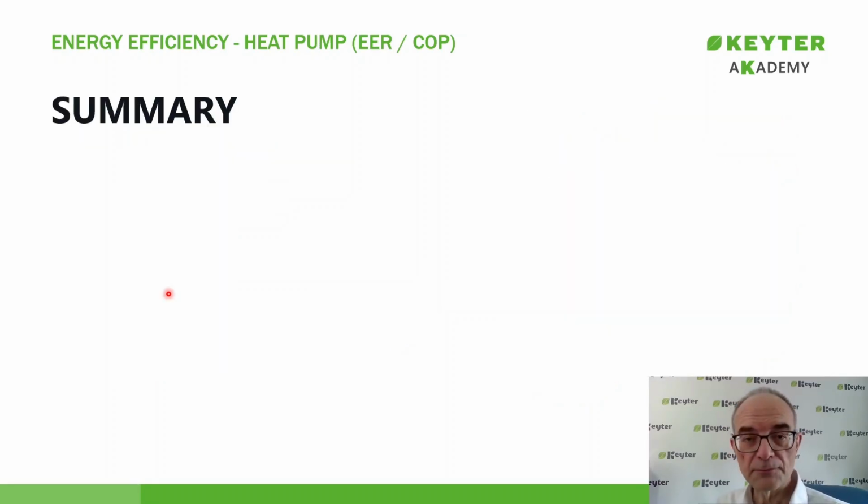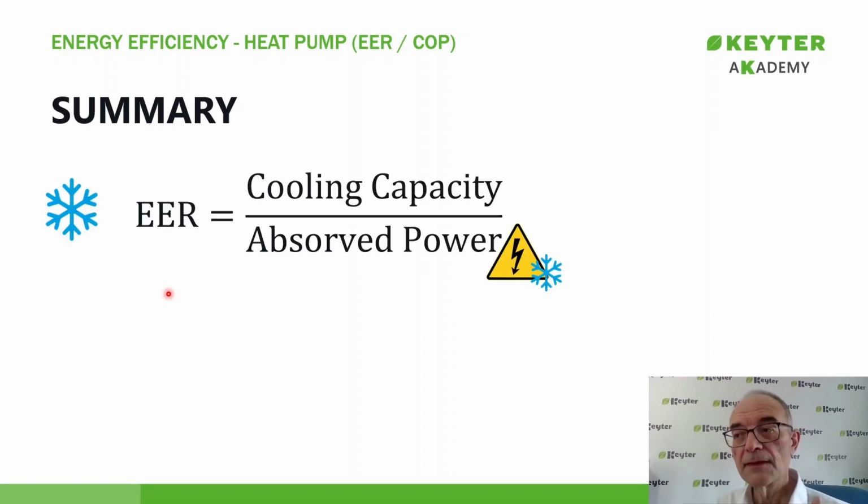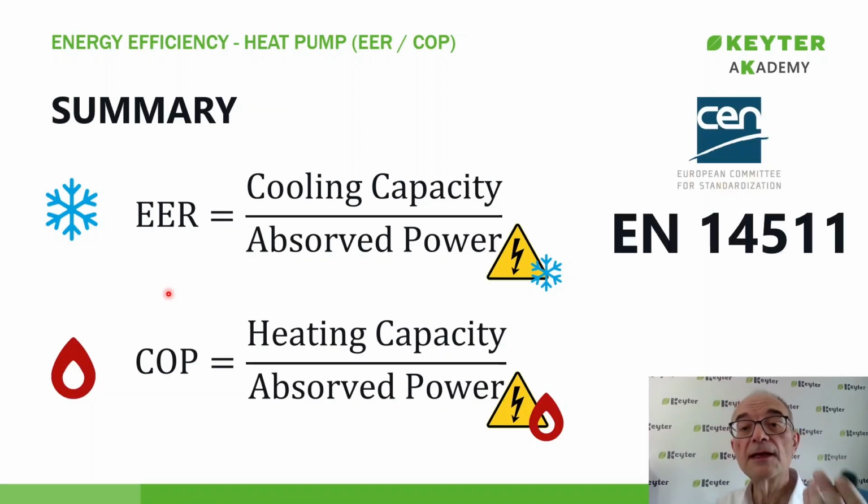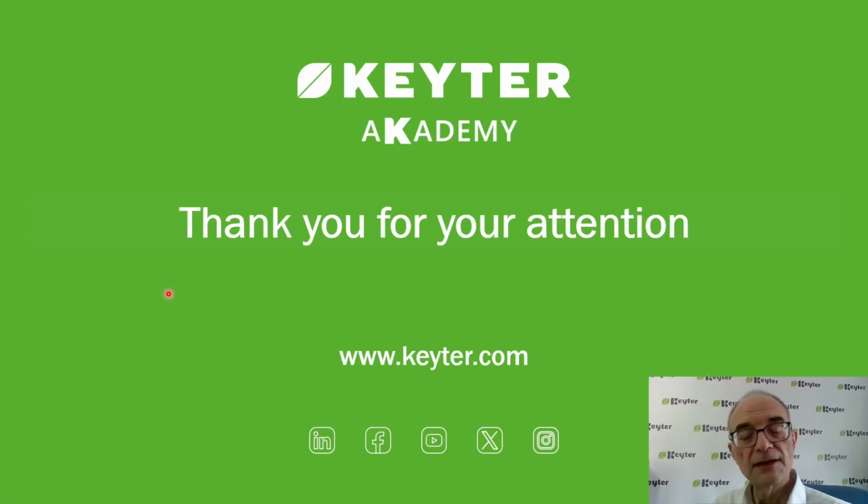To sum up, and this is the important part I want you to remember, for cooling mode, we'll calculate the EER, and it will be the ratio between the cooling power delivered by the heat pump and its energy consumption while operating in that mode. The COP is precisely the same, but now working in heating mode and always operating under the EN 14511 standard. That's the important part. You should know that the EN 14511 standard sets the guidelines for these types of tests.